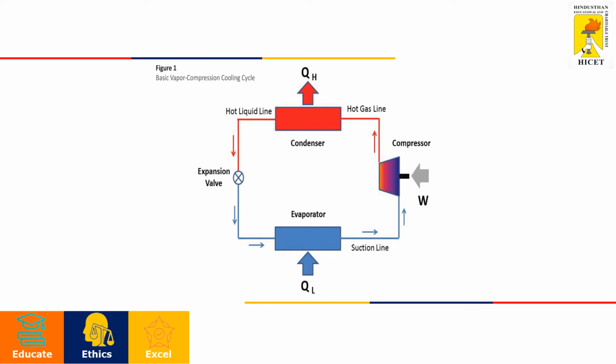You may ask, why a compressor? What is the purpose of the compressor? In order to make the condenser work 100% efficiently, the input should be of high pressure. Here the gas comes out at low pressure, but the condenser works efficiently only at high pressure.